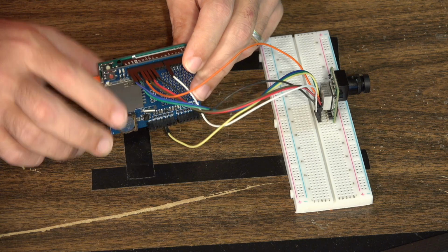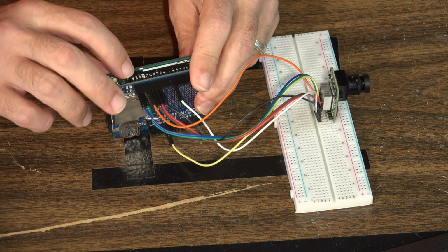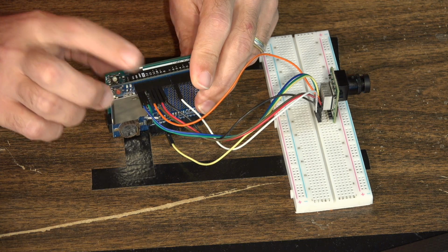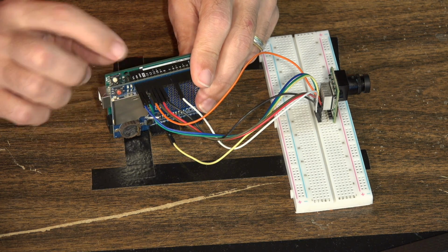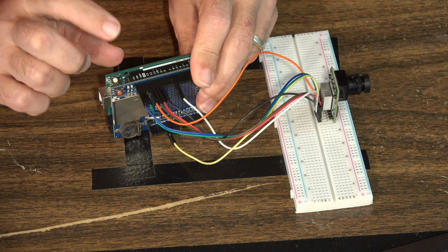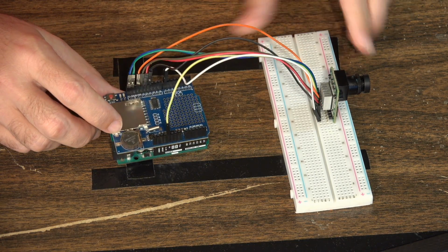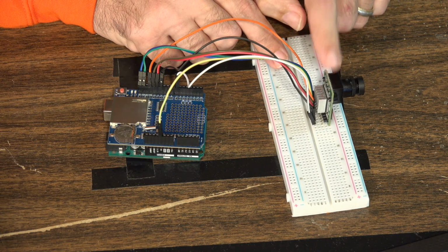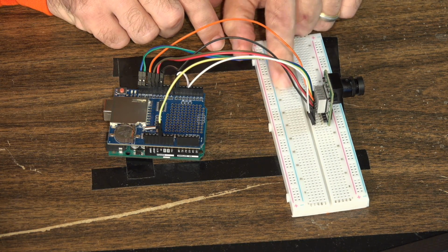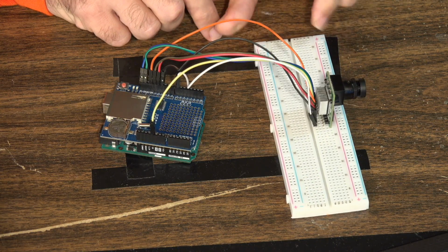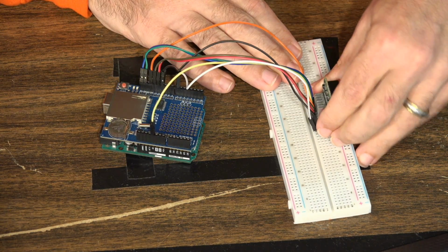So do make sure that whatever data logging shield you're using, the SCL and the SDA pins go all the way up into the data logging shield itself. If not, you're just going to have to modify your wiring a little bit so you can plug the Arducam in. Beyond that, the only other real customization that I've done is I have plugged the Arducam into a breadboard, and so this way it's a lot easier to position and aim the Arducam for your project.